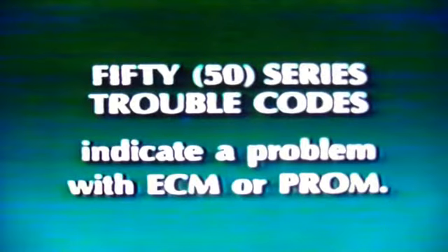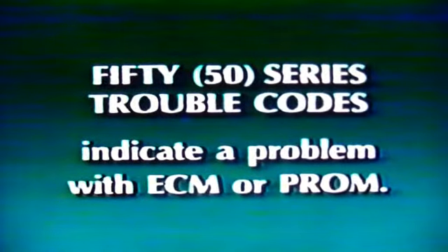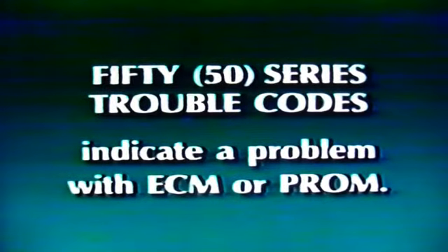We would proceed in this manner for all the trouble codes stored in the ECM memory, taking them, as we've said, in numerical order. However, there is one exception. If you find a 50 series trouble code stored, remember to do that one first. Trouble codes in the 50 series indicate a problem with either the ECM or the PROM. And you want to resolve these types of problems first because a defective ECM or PROM can be the cause of the memory storing false trouble codes.